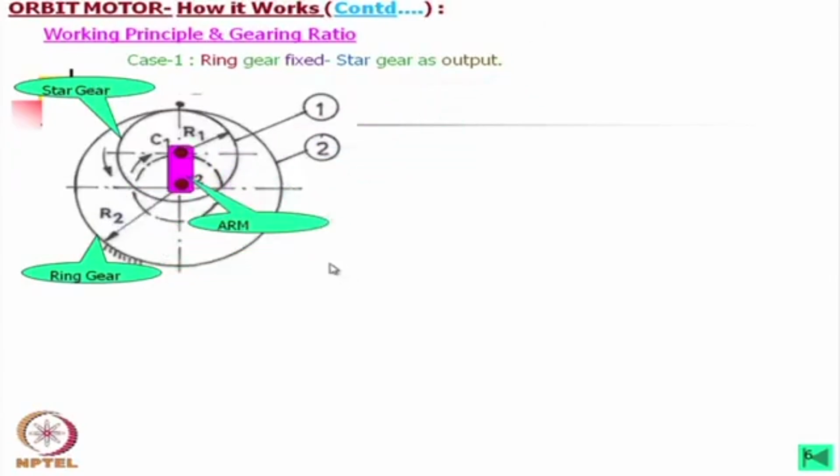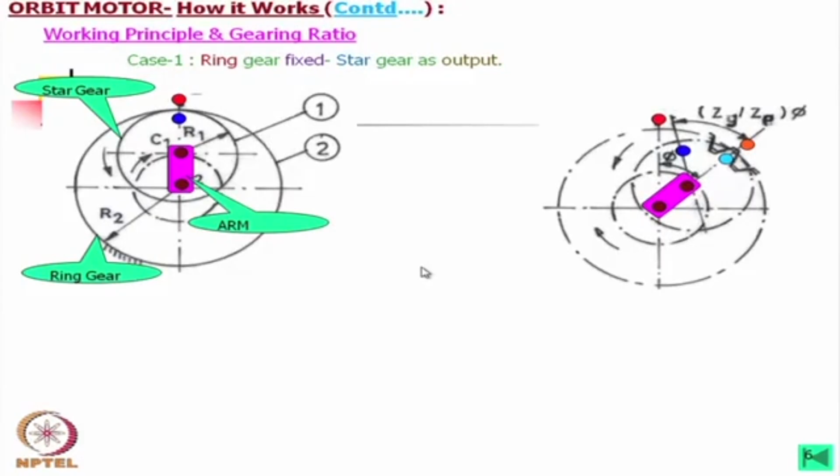Next, imagine the arm. This arm means that on a single plate, this gear is pivoted here and this gear is pivoted here. Now, we consider two points on these two gears. In the next phase, we give the whole unit an angular motion by phi.